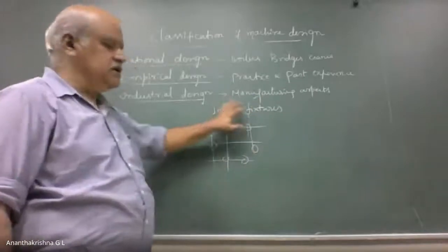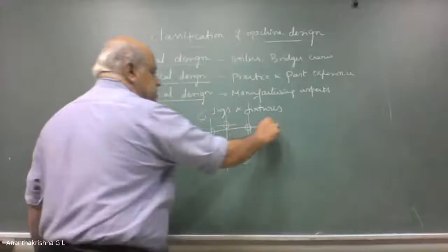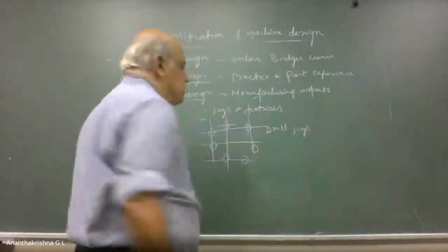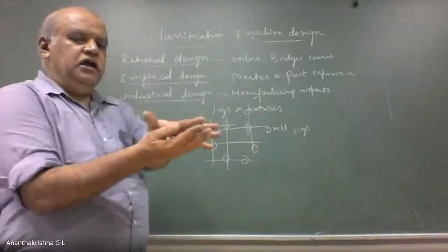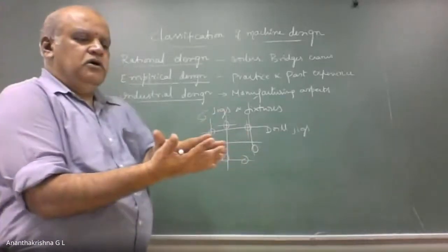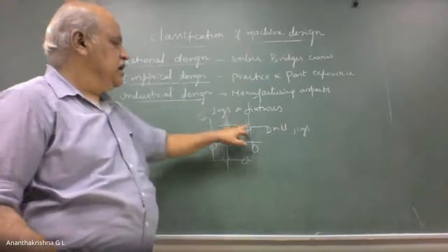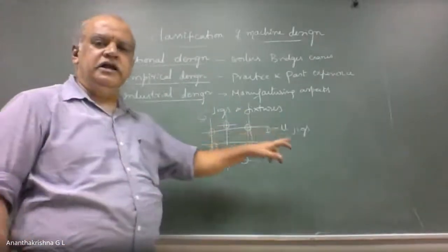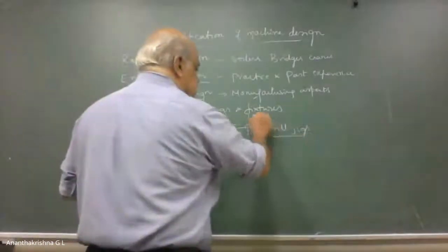So they use drill jigs. They produce a master with the greatest accuracy, then place that on the component, and drill through those jigs, thereby producing components en masse with the greatest accuracy.